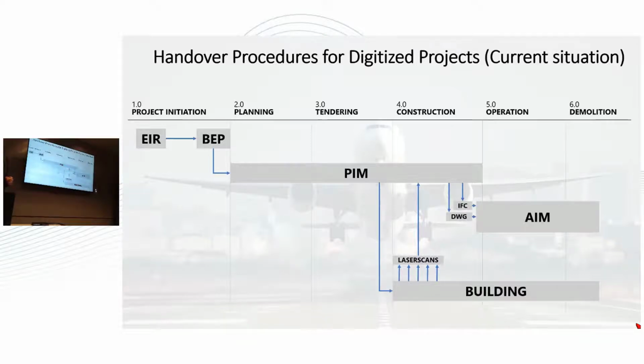But what we need as well is a DWG drawing from every story, because we also need 2D drawings. In Austria, this is a question of the law. They say we need 2D drawings from every story to operate the building. So we have to get it. And this is something we can't transport in an IFC file. But then there's another thing.